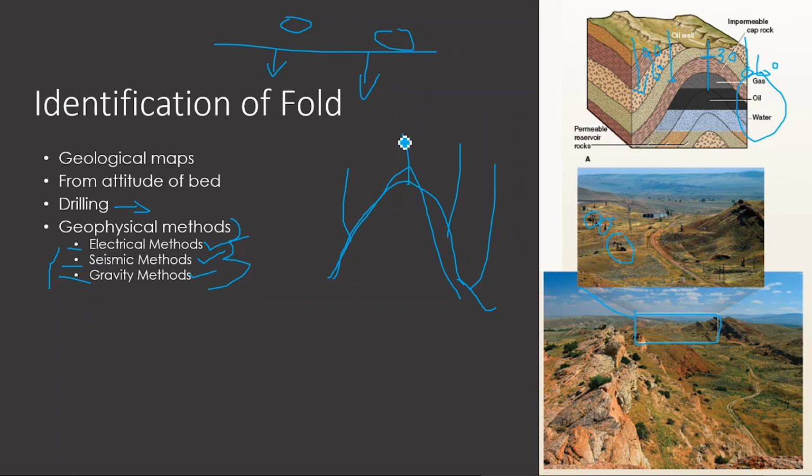And the seismic method is something where we use seismic waves. These seismic waves, we know, are the waves produced by an earthquake. And if there is no earthquake, then what will we do? We will generate an earthquake. We cannot generate an earthquake, rather we can generate a miniature form of earthquake. It is nothing but making a small hole and taking a bomb, or a cracker or something, which blasts. That blasting creates energy, which passes through, and we collect the signal from different areas, so that will tell us the structure below.